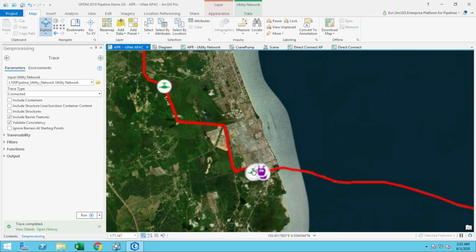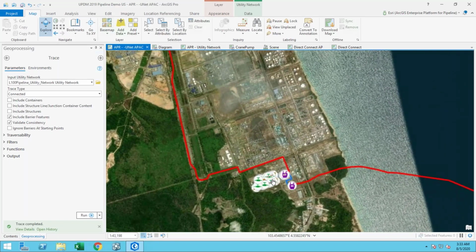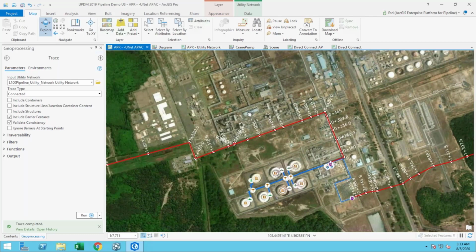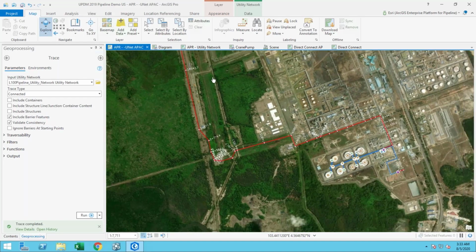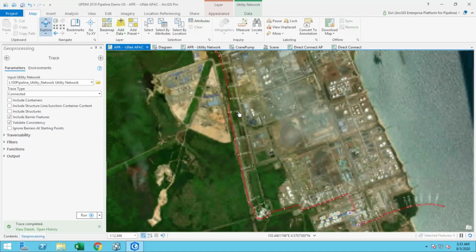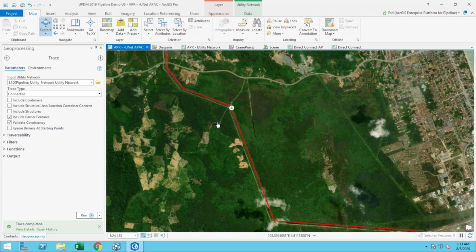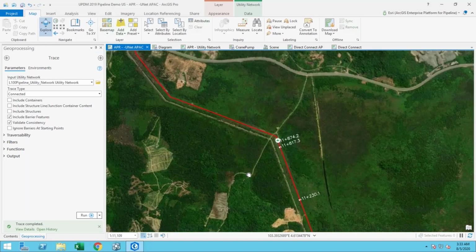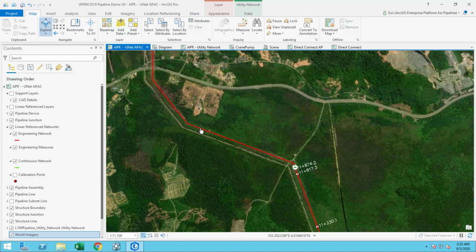So now let me show you a little bit of that transmission facility. So coming out of that storage facility and then back into the transmission system, I'm back onto that linear referencing network. And I actually want to show you how I go ahead and set this. So I'll go up here to this other end of the line because I've set my linear referencing system up into this mainline valve, and I have just pipe here, but no linear referencing yet on this part of the system.